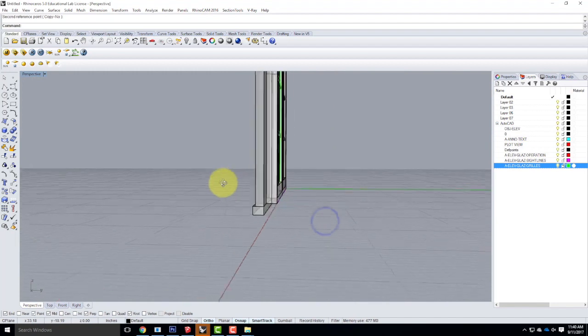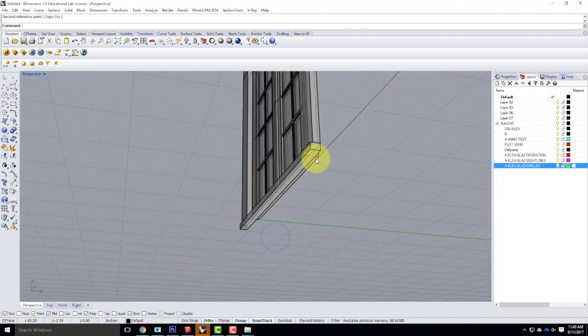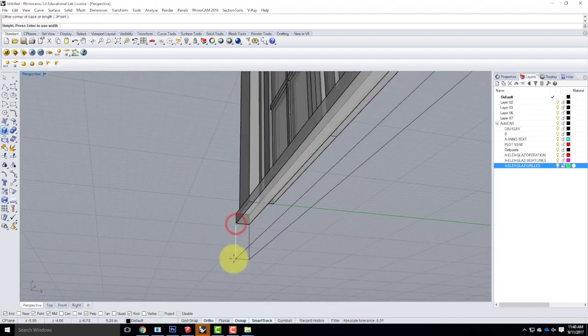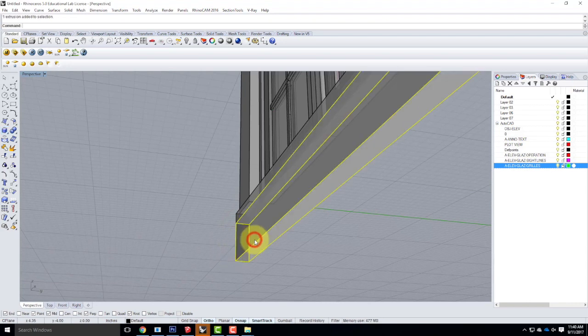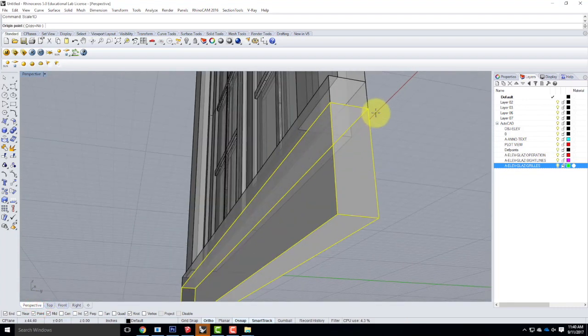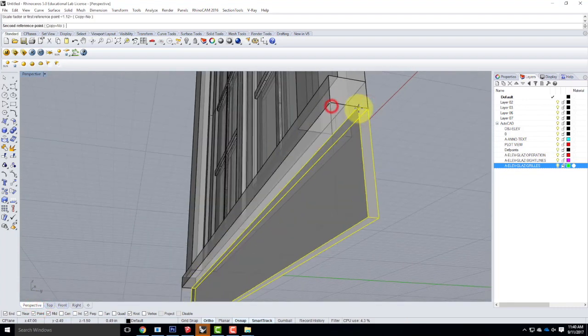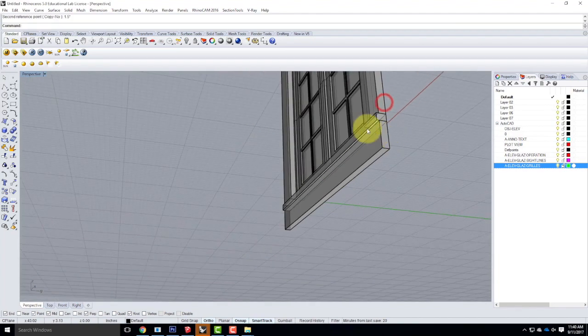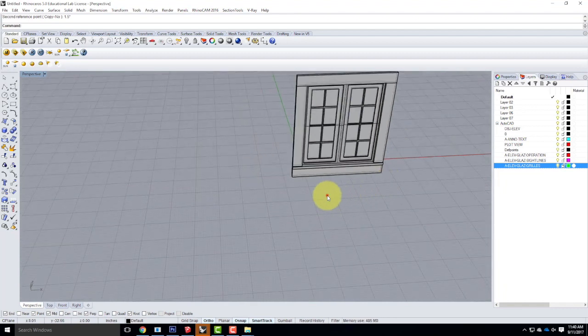Like that. Slight little reveal in the sill. Let's go one little piece of trim underneath this. So I'll just make it as big as this is, but we'll go down negative 5.5 inches there. Scale 1D. And we'll take that at 1.5 inches like that. So essentially what I did is I just built out the trim that goes around the window.